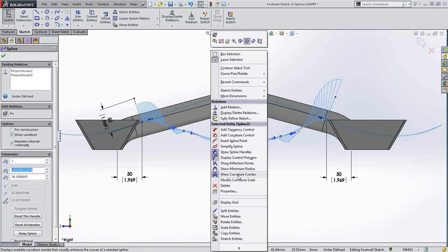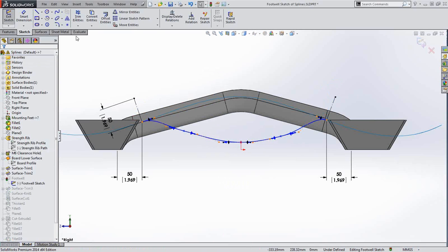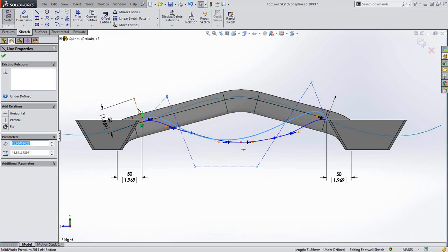Okay, but what SolidWorks 2014 has added is a completely new method for sketching splines if you want to use it. It's called style spline. You'll notice as I'm sketching a new one here, just on top of what you see, I'm creating these control polygons practically, these lines. So instead of all the spline points, I've created these lines, and you can see how it's mapping the spline to that general shape. So let's add some relations.